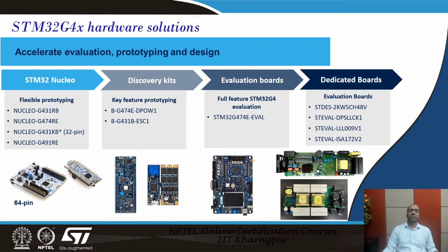There are several hardware platforms available for STM32G4 microcontroller evaluation. The first category is the STM32 Nucleo boards. These are very cost-effective general-purpose boards in which the microcontroller is in the center, while all the GPIO pins are available at the ST morpho connectors and some of the pins are available at the Arduino Uno connector. These boards don't require any external debugger, as the debugger is mounted on the board. All the STM32G4 Nucleo boards are listed here.